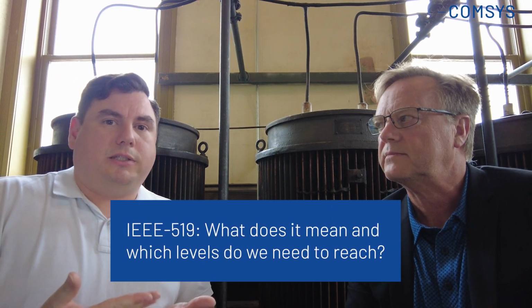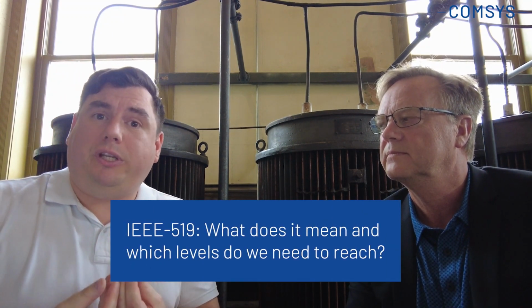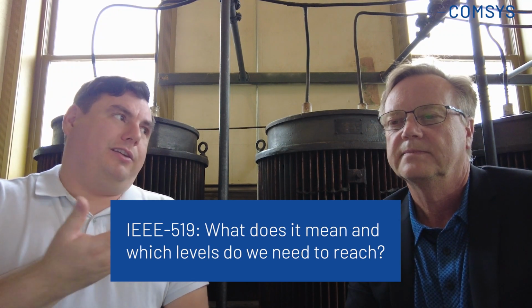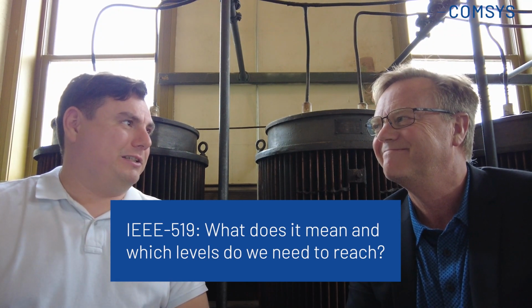Otherwise, we can talk a little bit about the standard itself. So IEEE 519, what does it mean? What levels do we need to reach in this standard? And you know what we hear typically from the customer: I want to have 5% IEEE 519, and this is of course not the case. IEEE 519 doesn't say it always needs to be 5% in the current. This is something that some marketing people came up with and really pushed out, that it's always 5%. Of course, it's easier, but it's not quite the truth.